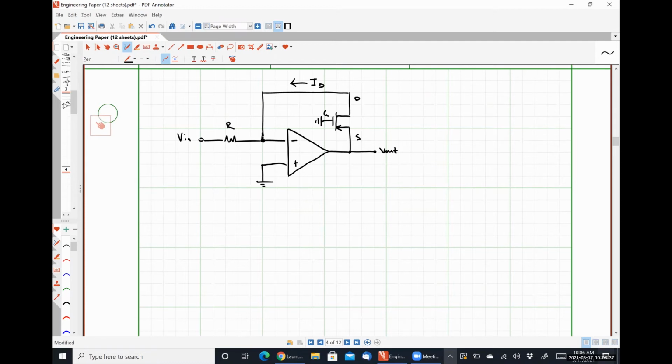Because the drain and the gate are tied to the same potential of ground. And so when Vin is equal to 0, Vout must inherently be VTHP higher than ground for our PMOS transistor to have to be in saturation and about to conduct current in that direction.